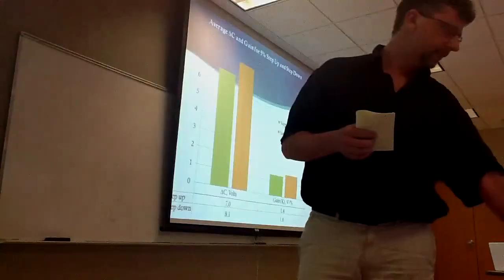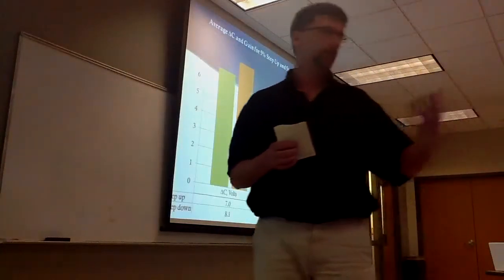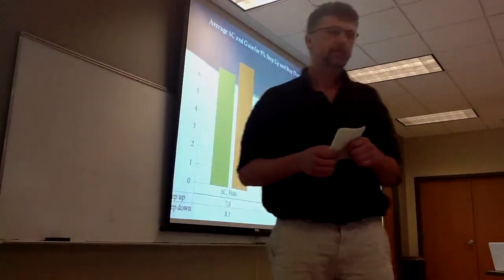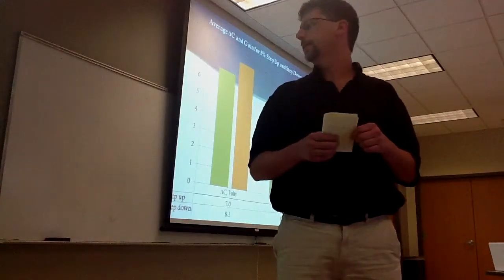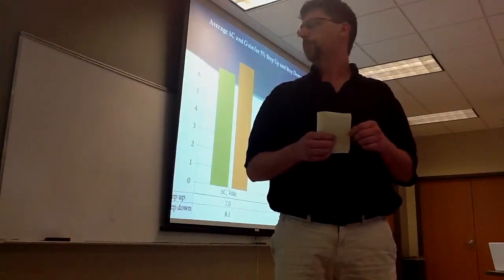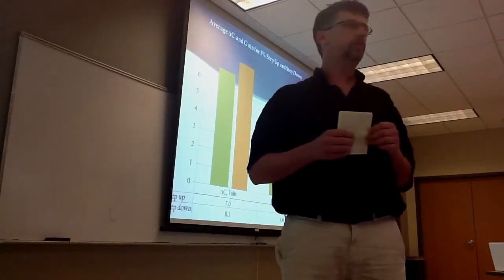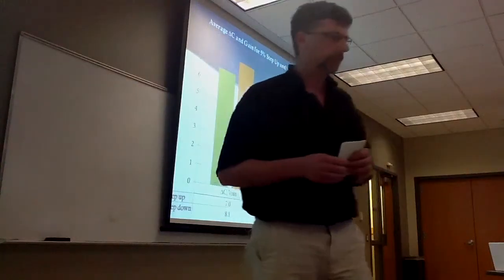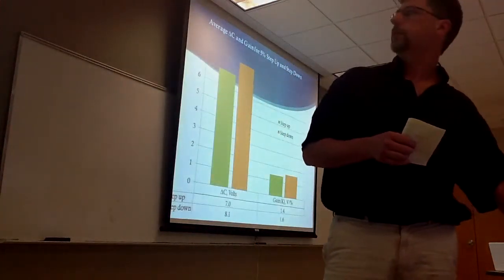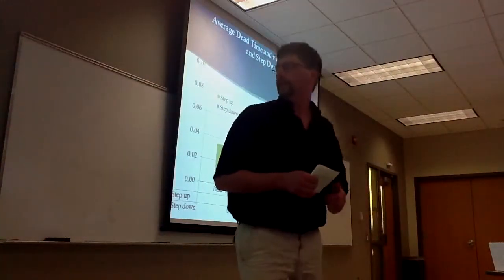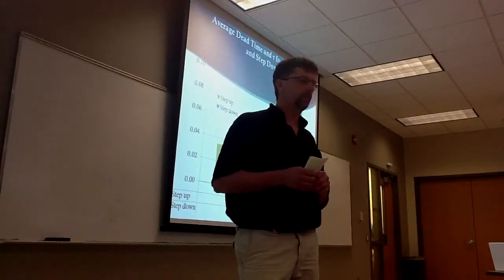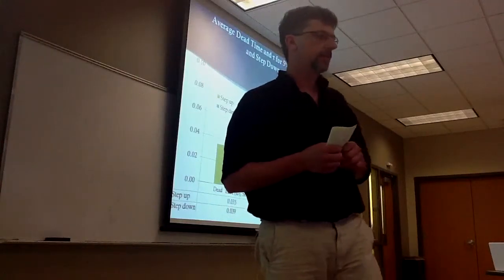Again, we plotted several of these step up and step down to be able to calculate the different parameters for our system. The primary one that we were concerned with here is gain, 1.4 volts per percent for the step up and 1.6 volts per percent for the step down. For the steady state operating curve, we had 1.8 volts per percent, so it's fairly close. Our dead time for the step up and the step down was very similar, 0.035, 0.039, and the time constants as well were also very close to each other for the step up and the step down.